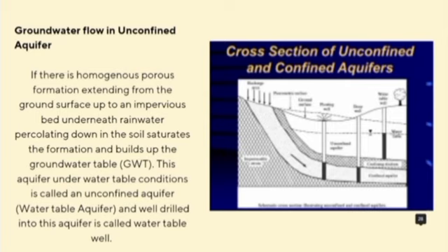And that water table has a depth. The depth of the water table varies according to factors such as topography, geology, season and tidal effects, and the quantities of water being pumped from the aquifer. Always keep in mind that unconfined aquifers are usually recharged by rain or stream water infiltrating through the overlying soil. So, it is very opposite to the confined aquifer.